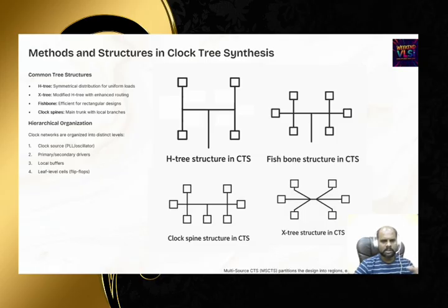Okay, what is the disadvantage? Not very routing friendly. That's why people don't go for it, because we cannot route in an X fashion, the diagonal fashion. It is very complex to achieve that pattern, and it has higher wire length and power consumption, and less flexibility for irregular sink pins. If the pins are irregular, then there is no flexibility here.